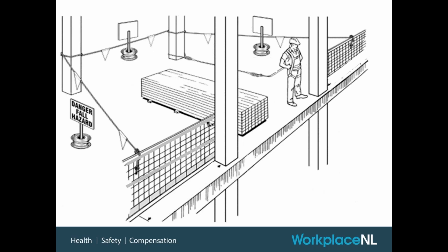So we've got lots of good anchor points potentially in this work area. We've got these big massive concrete columns that are perfect for tying off to. In this particular scenario, the worker is assisting a crane to lift materials up onto this floor. So there's a crane operation going on outside the picture on the right-hand side. This worker's job is to grab the tag line as the crane approaches with the load and bring it in, and then have it sit there next to them in their lay down area, I'll call it.